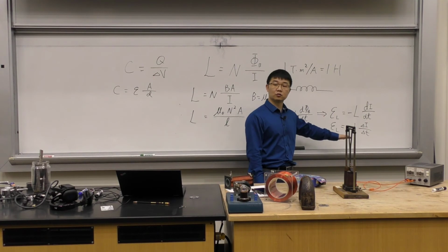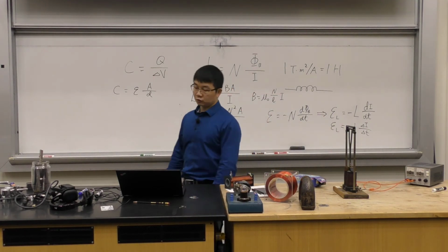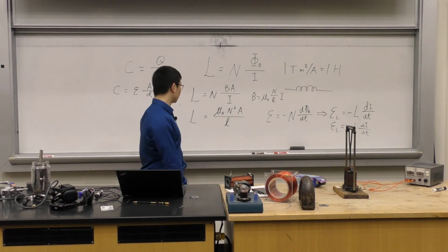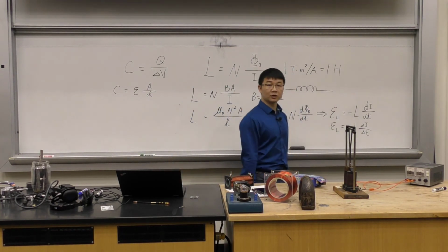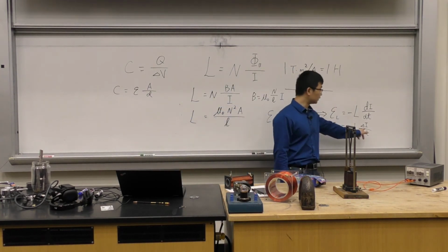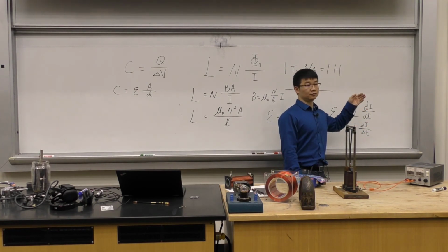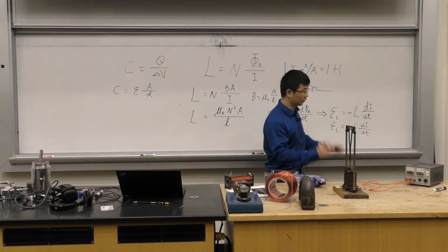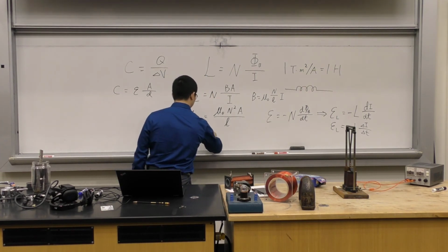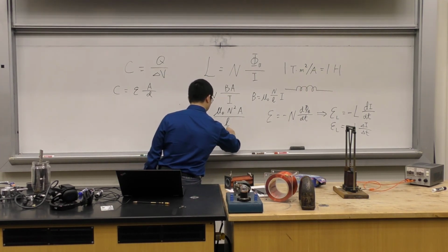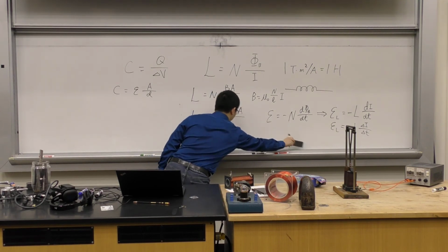But when I use this equation, I always do that in 2 steps, right? When I calculate the magnitude, I'm just going to get rid of the negative sign, because even the changing current can be negative if the current is decreasing. Forget about all the negative signs. I would just use this to find the induced EMF.